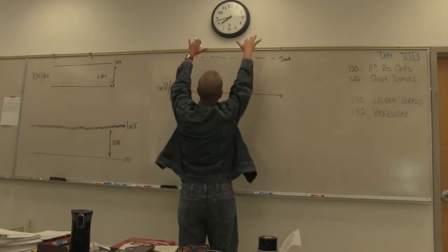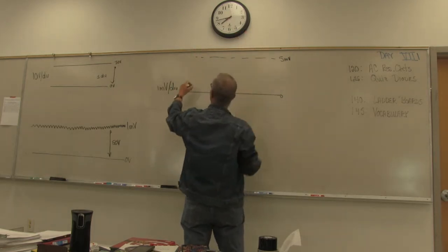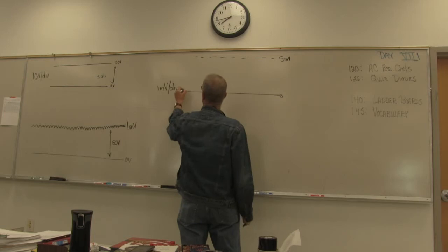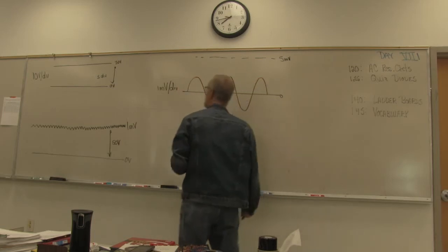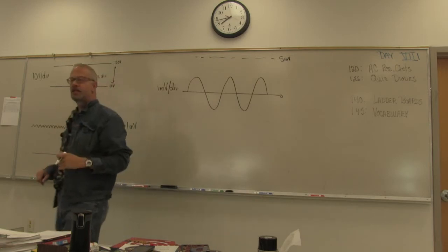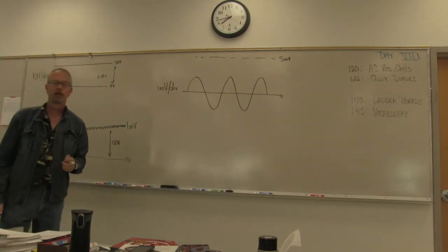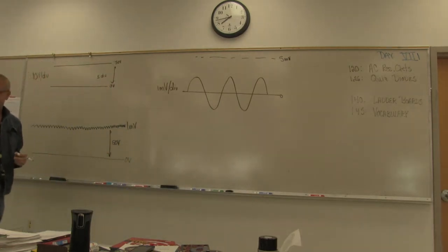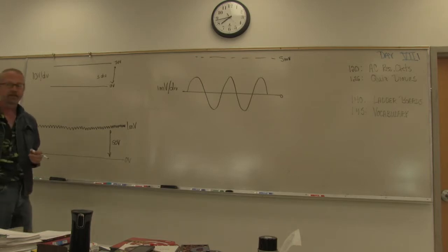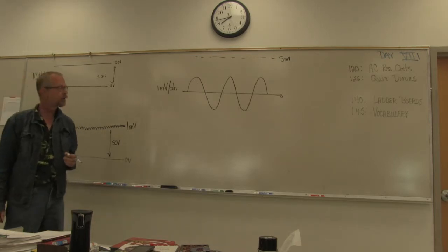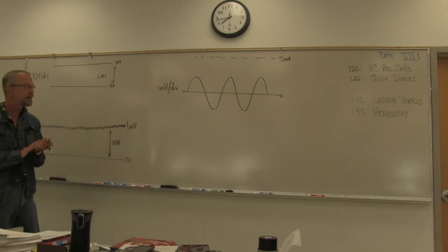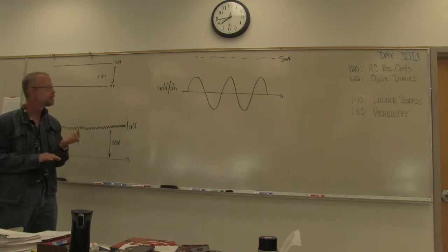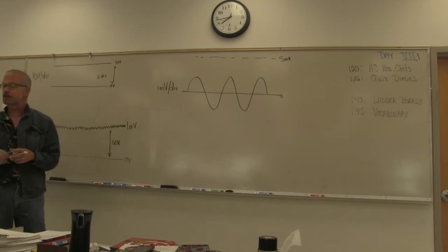And then that will bring that sky-high waveform down and give me my 1 millivolt per division because the DC has been eliminated. Okay? That's one of the things that you're going to have to become familiar with next quarter when you start working with the transistor amplifiers, because that's what you're going to see. You're going to see combinations of AC and DC in the same circuit.